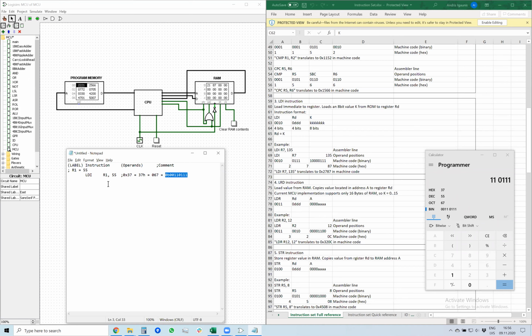C only accepts decimal numbers, hexadecimal, and I think it also accepts octal numbers, but not these binary numbers. So unfortunately, in C you cannot write bits as they are, but in assembly language, all versions that I know allow this.